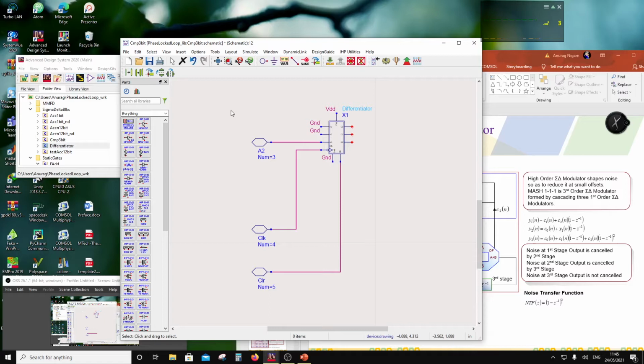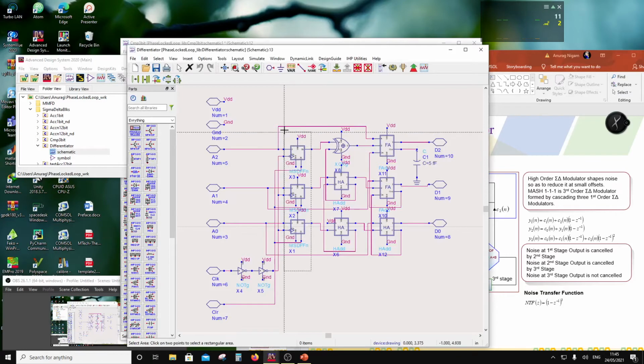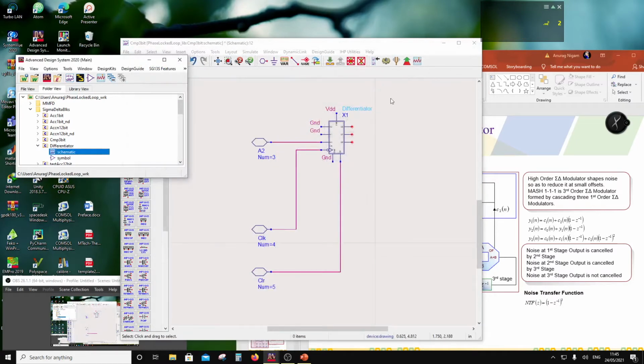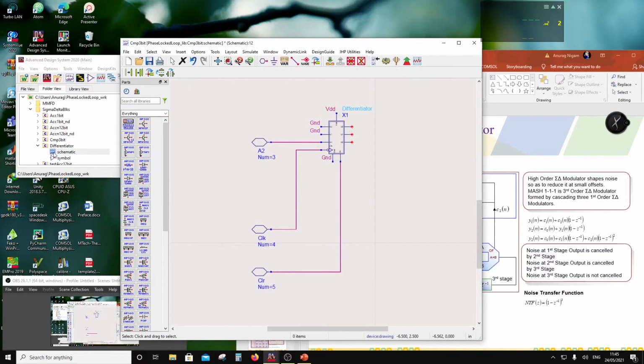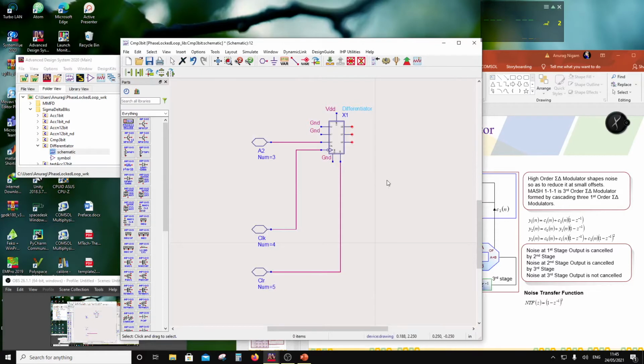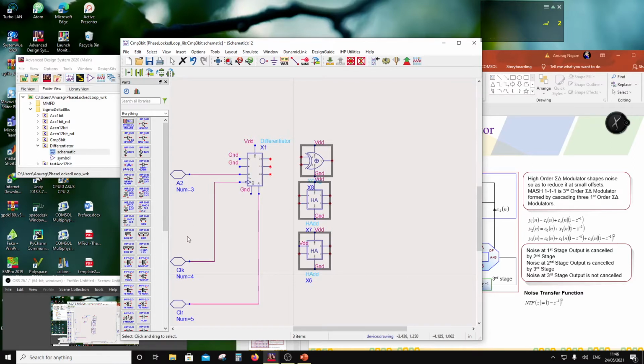So now I'll bring the A1 bit through a half adder, and D0, D1 and D2. So I'll have two half adders and an OR gate. Okay, so I'm going to bring in two half adders and an OR gate, something which is similar inside the differentiator, right? So it's like this, two half adders and an OR gate. So all I need is these three blocks. Okay, somehow it doesn't accept. Control C, Control V. Okay, so what do we have here? Okay, we have got A1.